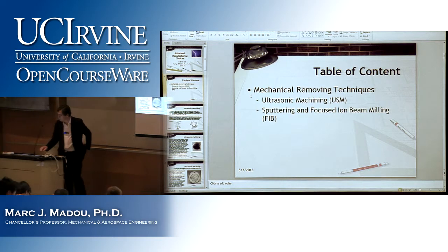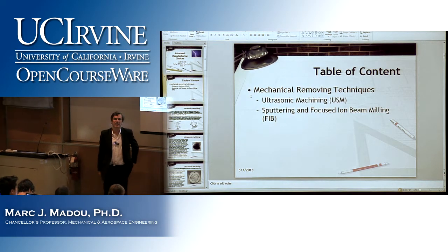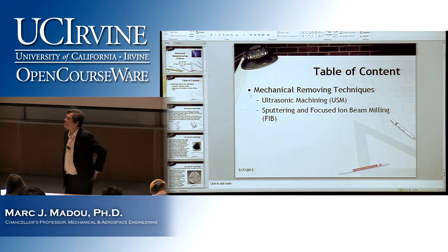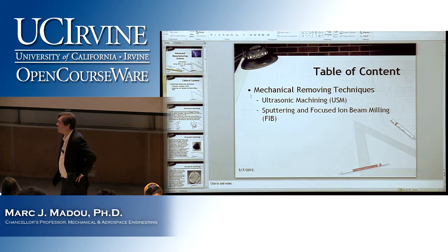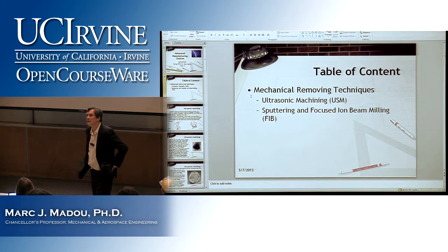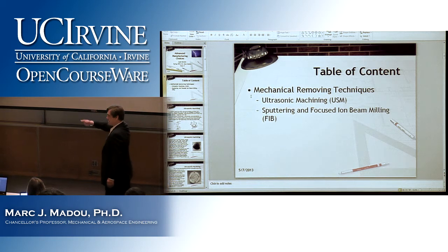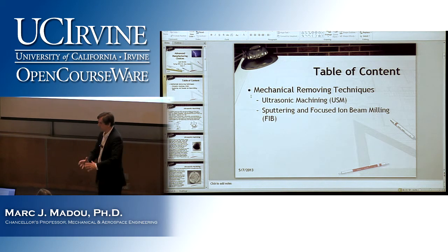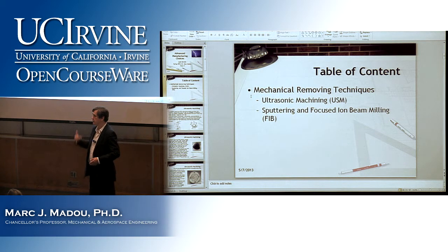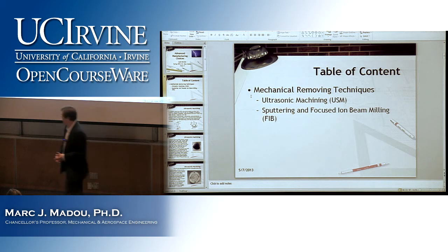What's the difference, by the way, between sputtering and focused ion beam milling, besides it's a different ion that you use as your brick, as your tool? There's another difference. Velocity of the particles? It's not like the input energy? Yeah, that's true, but something else. Focused ion beam concentrates on one spot, while sputtering goes over the whole surface. Right, that's kind of the primary answer. And so ions hit everywhere on the surface, they're not put into a beam. And in the case of focused ion beam milling, it's kind of the same process, except you make it into a narrow beam.